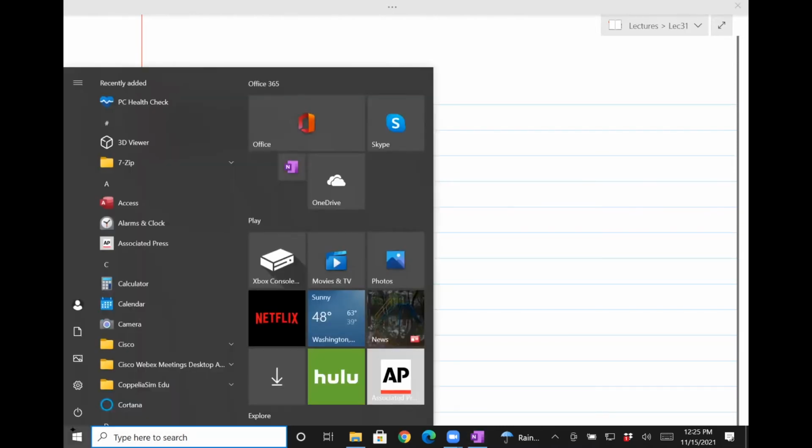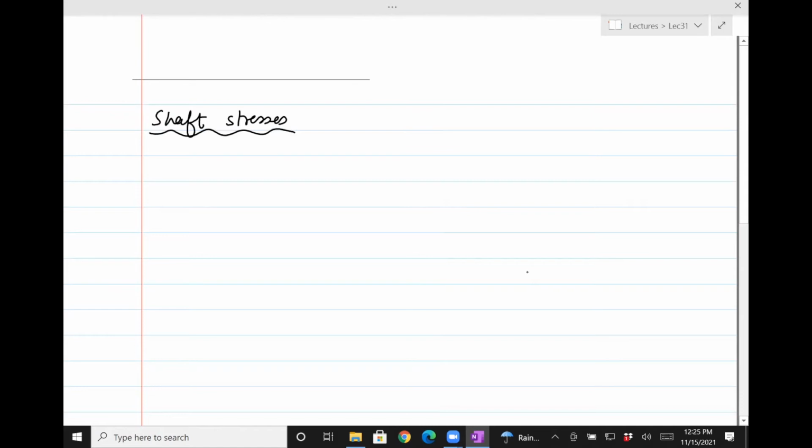When you say draw the shear force and bending moment diagram, you really only need one, right? You need both, because the shear force diagram tells you about the shear stresses. The bending moment diagram will give you the normal stresses, and those are different.